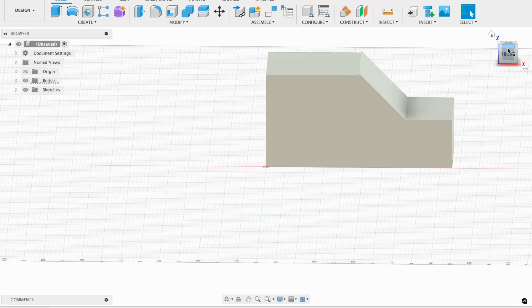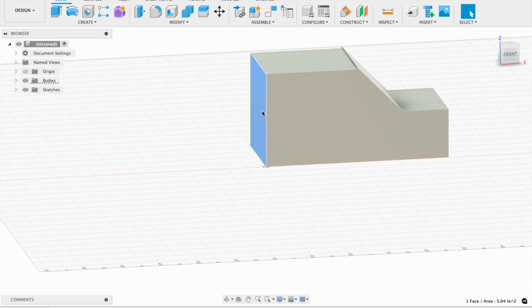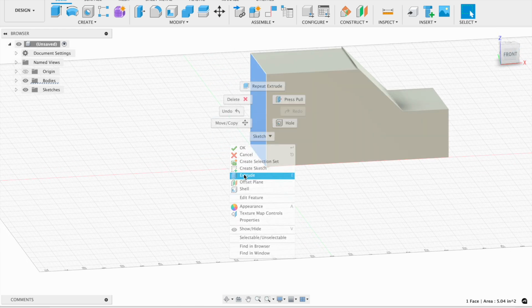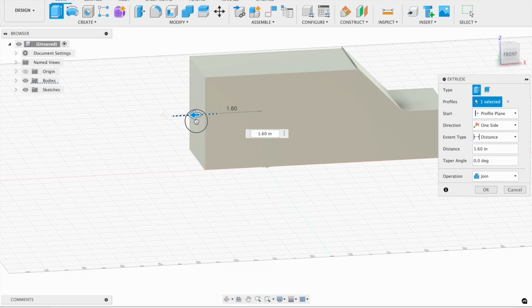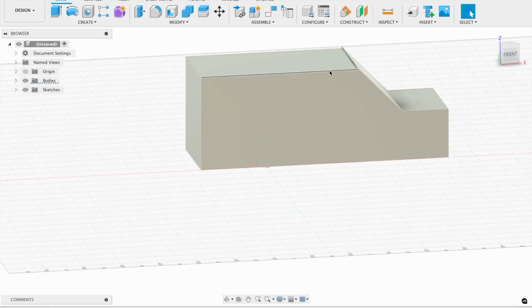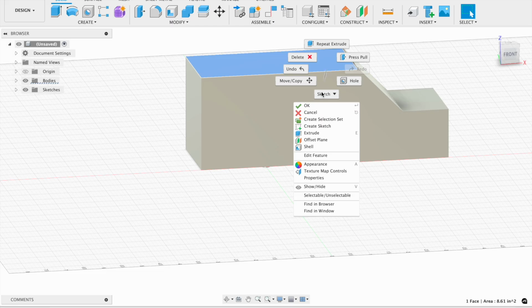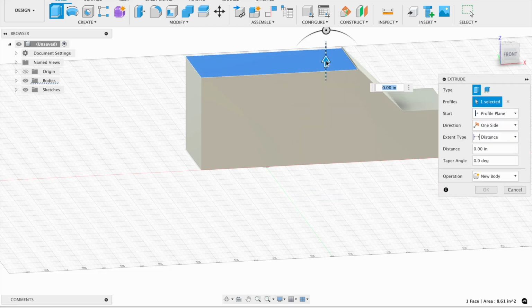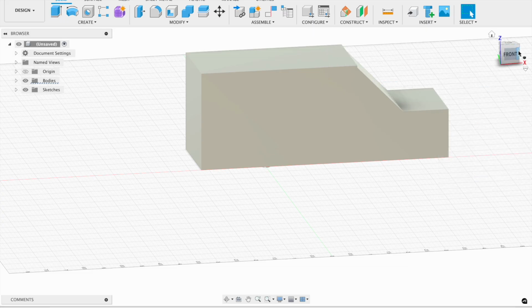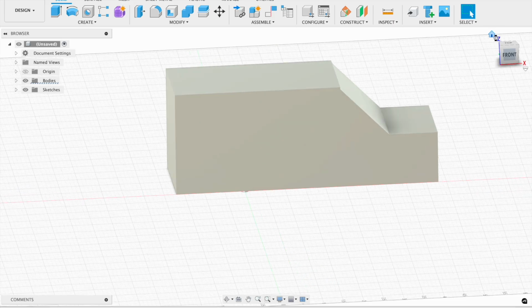The extrude tool will. It has to be something like the back of that food truck, which it will press pull. The extrude tool will also cut into most shapes. The press pull tool won't; it will just reset it to how it was. And the biggest thing with the extrude tool is that it has to be a closed geometry or else it will not work.